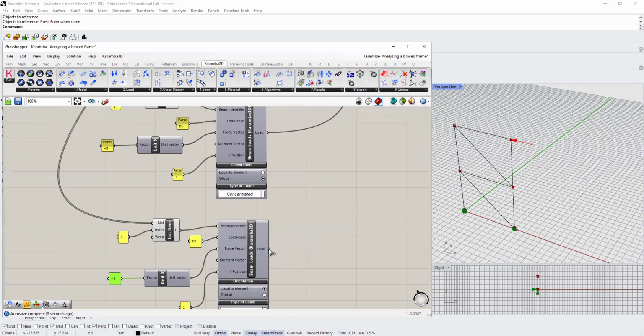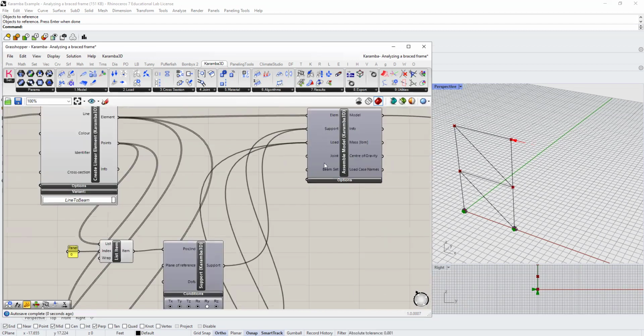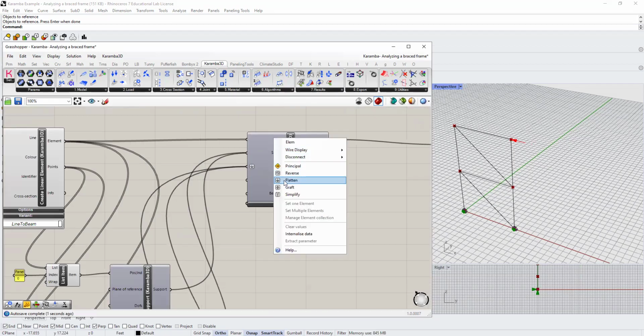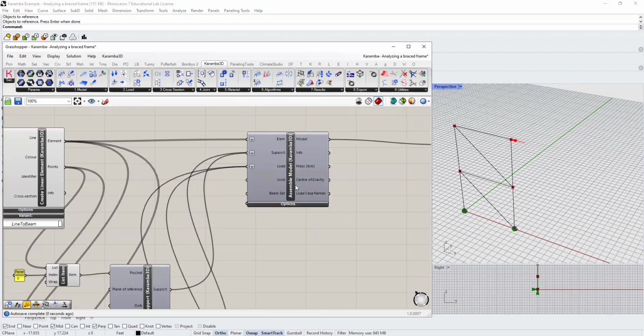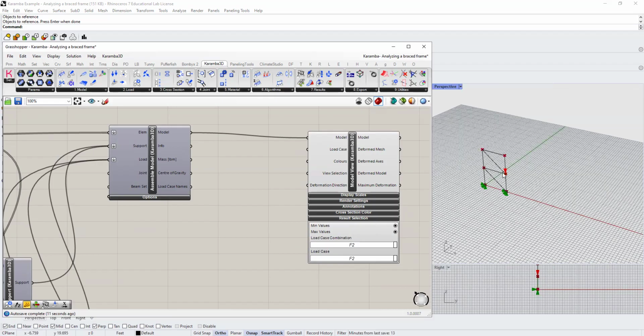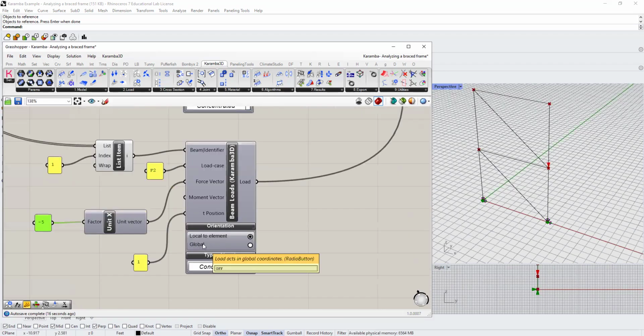Now I'm going to add this load case by holding the shift to the sample model. And I'm going to flatten all the elements, supports, and loads. Then still, I'm not going to see F2 because on the result selection, there are two options. So I switch to F2 and I see that the position is not correct because I forgot to change the orientation to global. So when I say global, then F2 will move here.